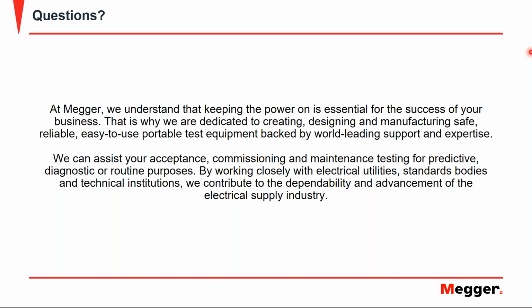What are the advantages and disadvantages of partial discharge versus VLF tan delta? Okay, so whenever we talk about partial discharge testing in relation to other types of testing that we do to evaluate the insulation of a cable, when it comes to VLF or tan delta, all of these types of tests are done to give you a complete outlook of the quality of a cable. And all of these different techniques are going to give you different information as far as what's going on with the insulation of the cable.